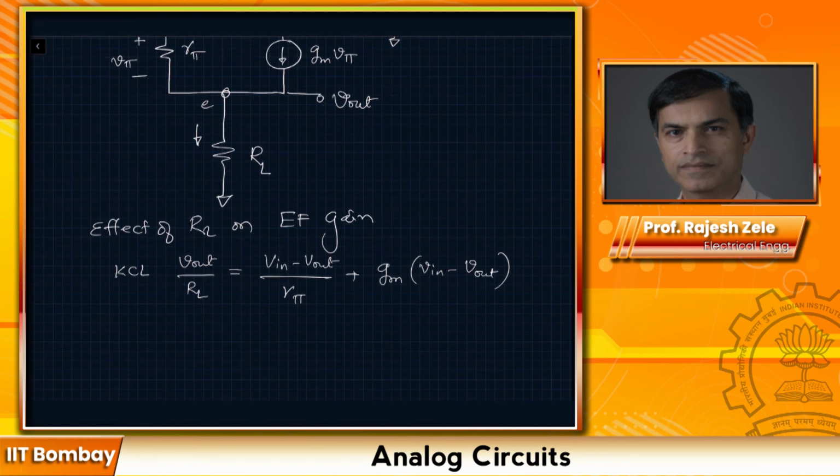So one quick trick I'm going to show you is sometimes we have conductance and resistance in the same equation, and it becomes a little bit cumbersome to handle. Now in this particular case, you can see that I have a transconductance GM, however I have resistance over here. So the equation would become a lot easier if I would just do an R to G transform.